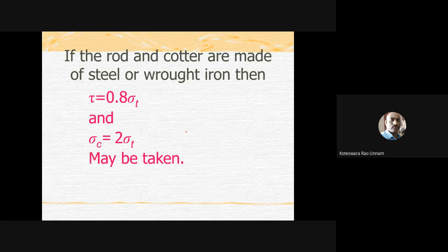Then equation D, shearing strength of spigot collar: P is equal to pi d2 t1 into 6 tau. Use that relation to find t1. Then shearing strength of spigot end: in that, a is unknown, so use that relation to find a. Then tensile strength of socket through cotter hole: in that you have D1 and d2, and t, so you can determine D1 using that relation.